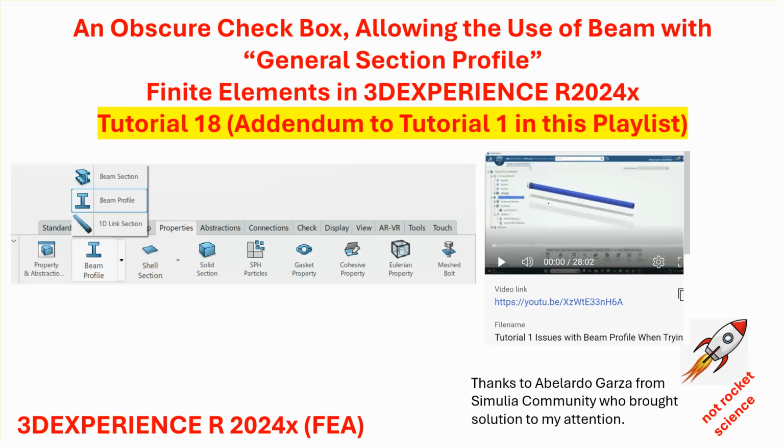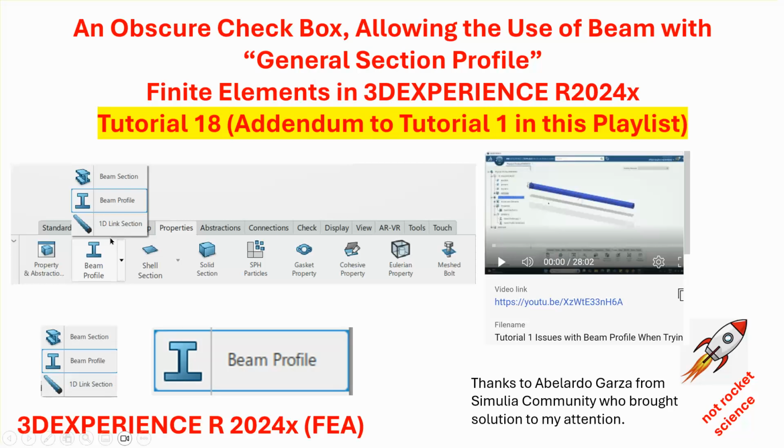And there is also an option which allows you to say, okay, I'm not going to give you the profile shape, but I'm giving you the properties that you need. In other words, the moment of inertia that you need about the local axis of the cross section. And then you work it out. So there is no profile per se specified, but it's called general profile, and you proceed from that point on. Let me show you what is involved when you do that.